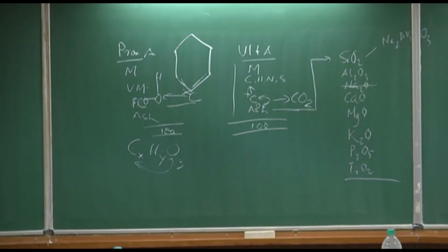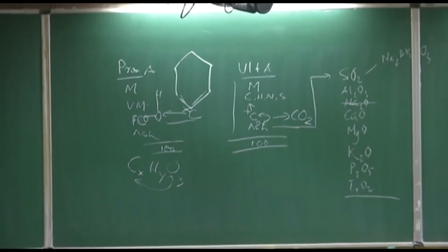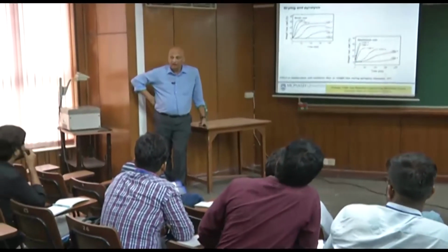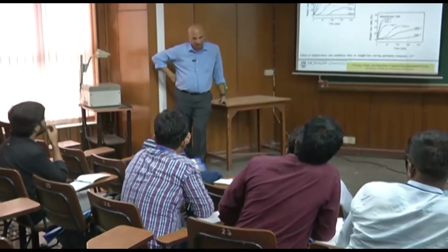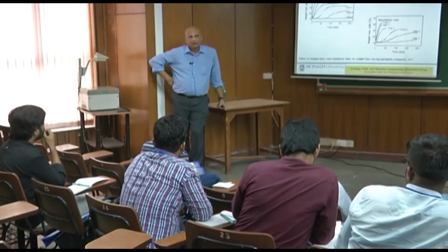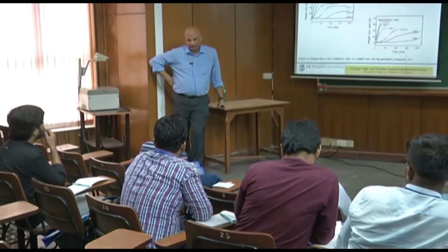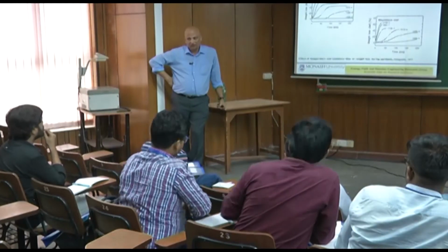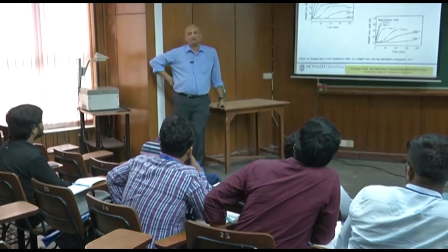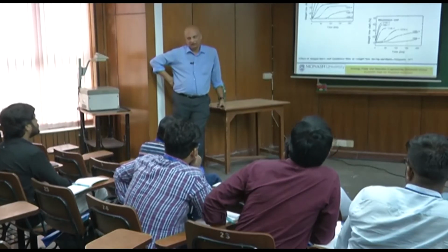I don't think that in a PF environment, where a fine particle is exposed to a high temperature very, very quickly, in a fraction of a second, in milliseconds, the devolatilization reactivity or the pyrolysis reactivity varies significantly between lignite or bituminous coal, not significantly.